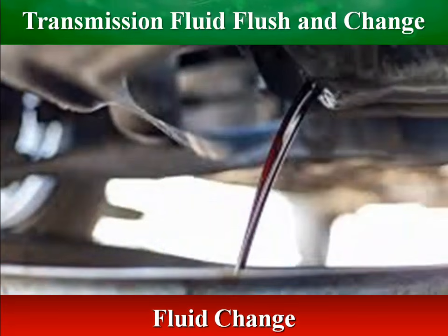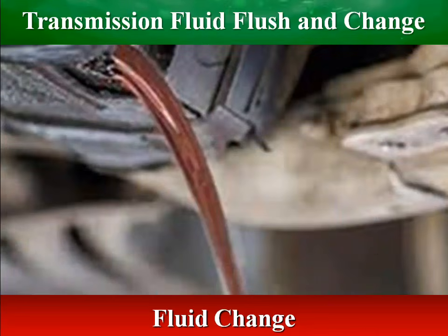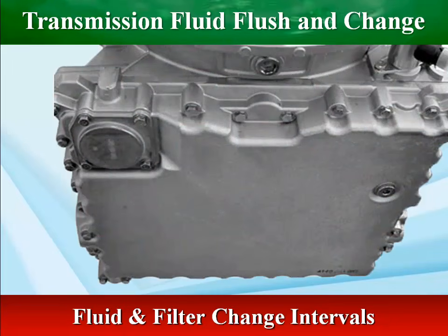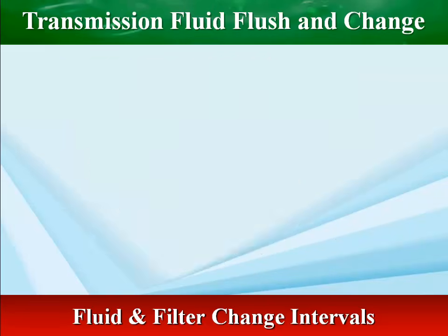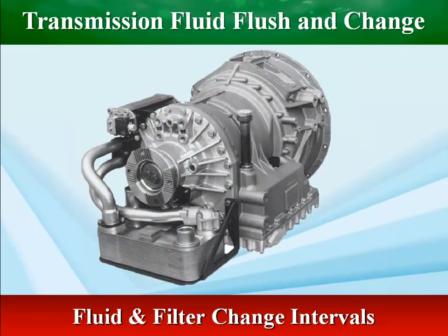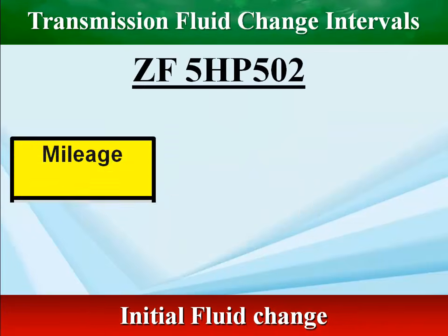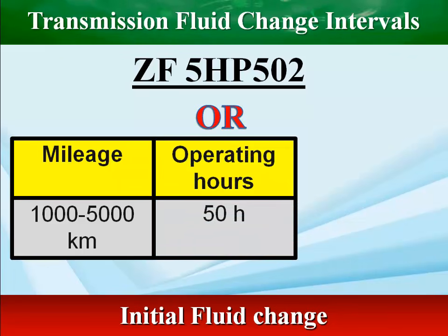A transmission fluid change simply drains the fluid with gravity. A change usually does not drain all of the fluid, but does allow you to replace most of the old with fresh transmission fluid. The fluid must be changed whenever there is evidence of dirt or high temperature, indicated by discoloration or a strong odor. More frequent changes may be required when operations are subject to high levels of contamination or overheating. The specified fluid and filter change intervals must be adhered to, according to the operating instructions of the vehicle.